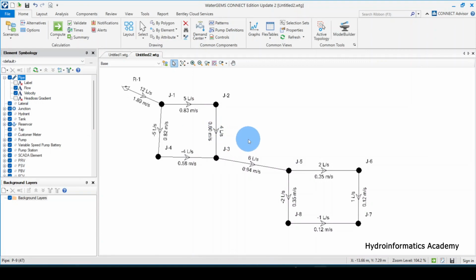I want to optimize my model by taking into consideration velocity first, then I'll shift to unit head loss. From here you can see the value that we are having is quite big, which is 0.89, and also the other values that we are having here, again we also need to change them. So let me first remove the flow. So now we have only velocity. If this is the value of velocity, I can see that it's quite big, and it's quite big because we are having a lot of head losses.